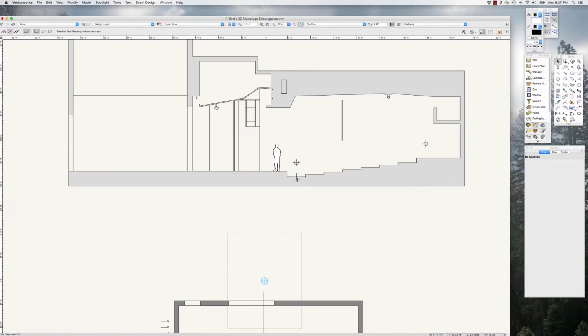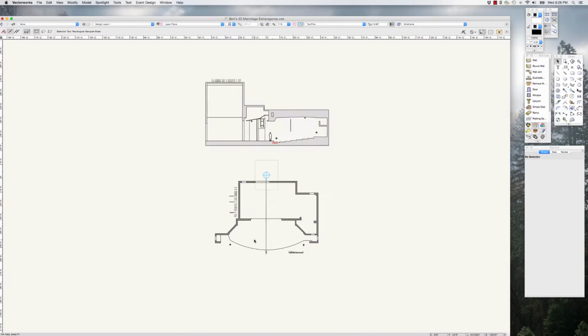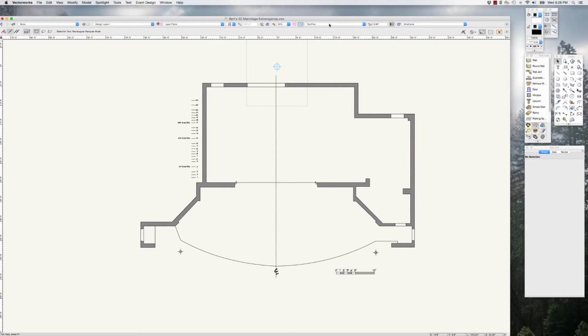There are a couple of decisions you could make. We could decide to make the actual floor 0 and not the stage floor. I think it's easier to make the stage floor 0 and extrude the stage floor down like we've talked about before, so that 0 is up here, the stage floor, not down here. Hopefully that makes sense. First of all, I'm going to make sure I'm in top plan view, and when we open the program we always are.